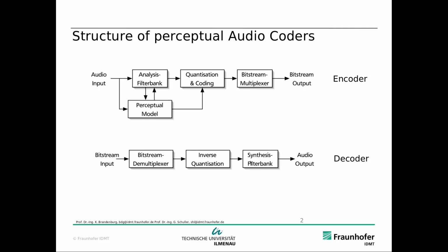So today we want to talk about filter banks, analysis and synthesis filter banks, such that they do this decomposition and still be able to reconstruct the original output if there's nothing else in between. So if you just take the analysis filter bank, take those subband outputs, feed it directly into the synthesis filter bank, then the audio output should be identical to the audio input except for a processing delay, right?